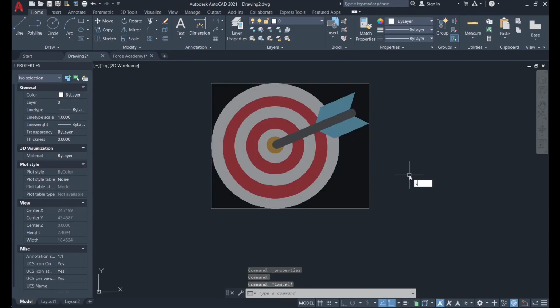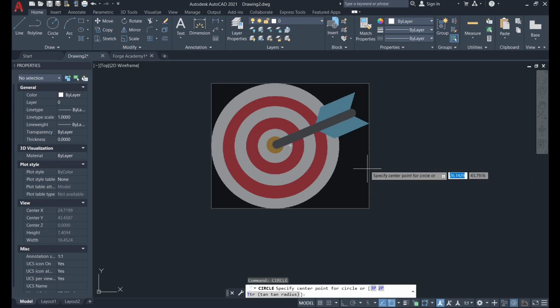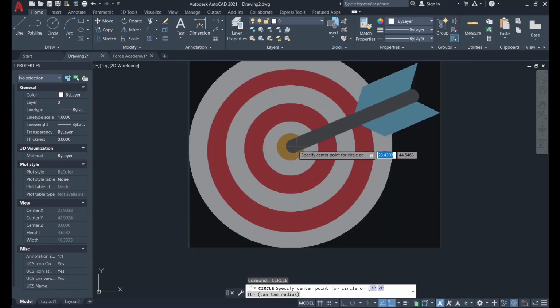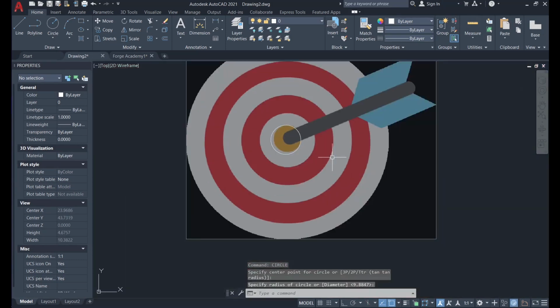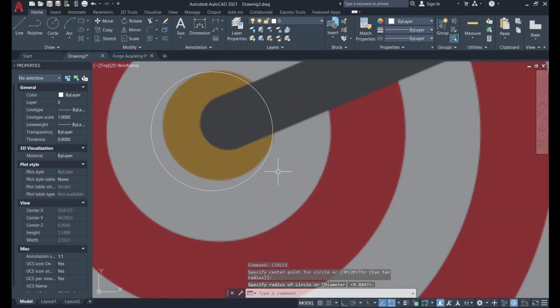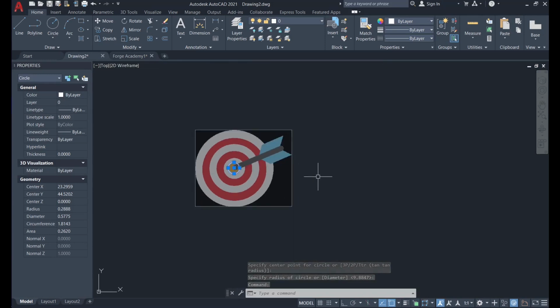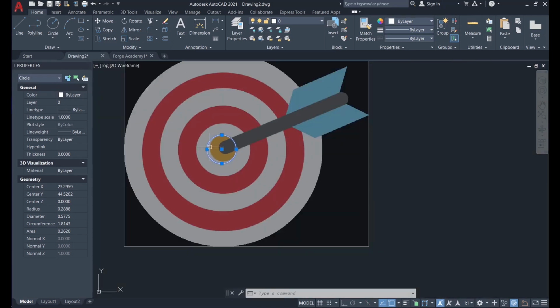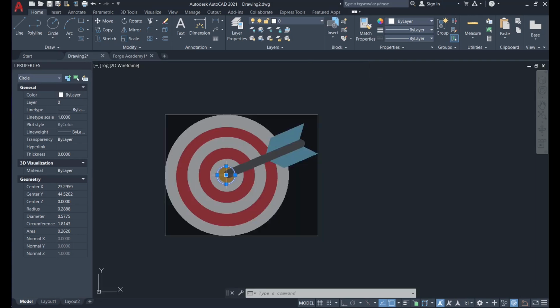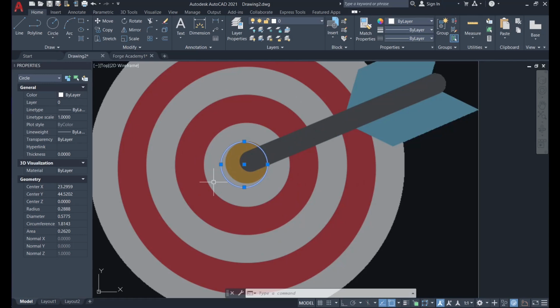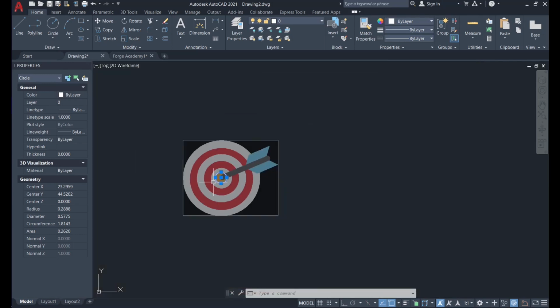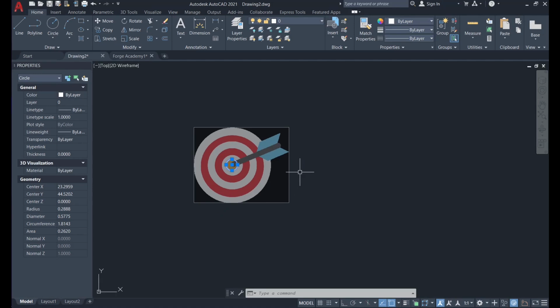and then you can use your useful commands to draw over the image and trace everything, or you can just trace a part of it or anything you need from that image. But as you can see, you cannot snap to the points on the image, so that is not very precise. In order to have a more accurate drawing, I can use the scale reference.